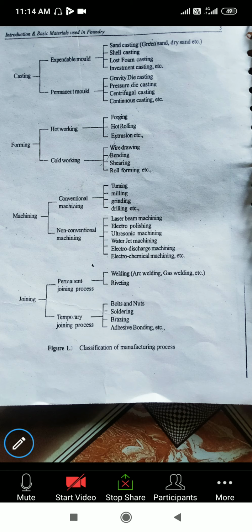Okay, now roll forming. Roll forming in cold working works the same way as hot rolling, only it is done cold. The only change is that the workpiece passing between the two rollers is in a cold condition, not in a hot condition. One more important thing: cold working conditions can only be applied easily to ductile materials.